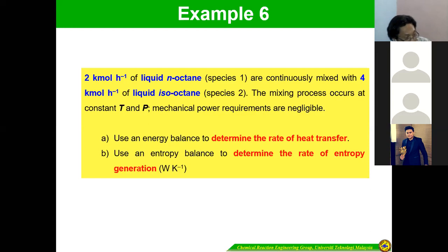So you bring it from 200 to 100 because that is the boiling point. There's no change in phase. Then from 100 to what? If the exit is a liquid, for example 30 degrees C, you need another step in the hypothetical path.